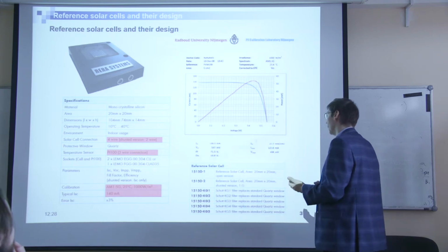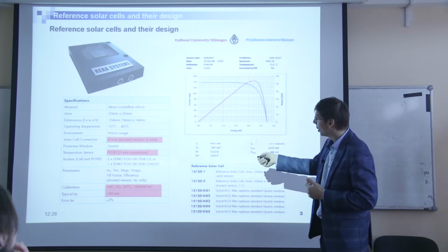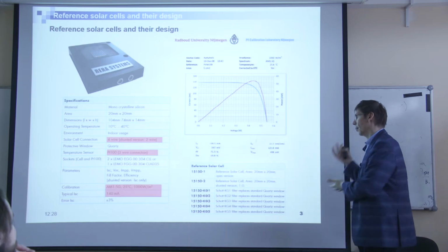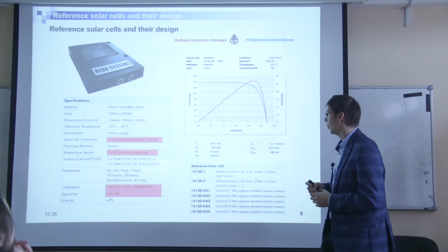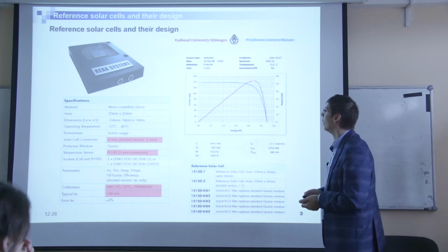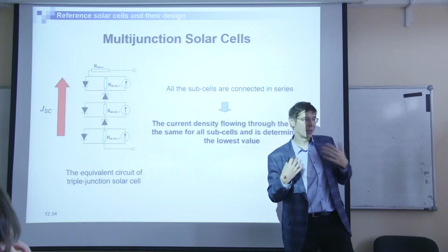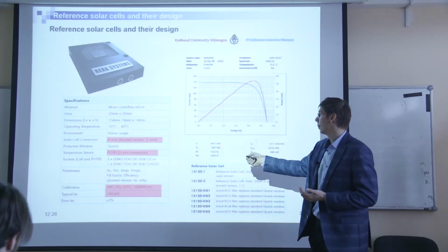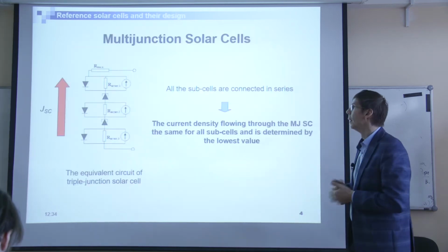Then if you want, you can also check other parameters, but it's just to test your IV curve measurement system, and it's not so strict. I mean, the main thing is this value. So it's more or less simple for single junction solar cell. You adjust the intensity and you can measure the IV curve.